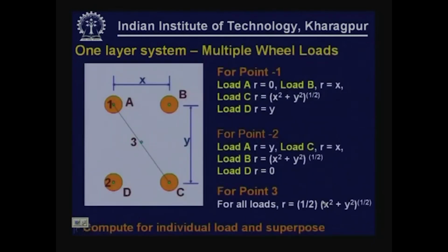Let us consider a 1 layer system which has to be analyzed for multiple wheel loads. What we have seen so far is a pavement system subjected to a single load, but if you have multiple wheel loads, for example, there are 4 wheel loads here, how do you analyze for stresses and strains at any given point? In this case, we have 4 loads A, B, C, D. We are also considering, let us say, 3 points, 1, 2 and 3.